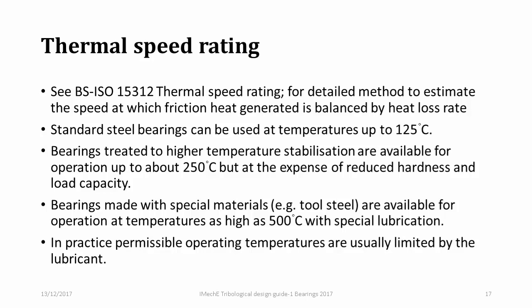Standard steel bearings can be used at temperatures up to 125 degrees C. If they are taken higher than this, it's beyond the tempering temperature, and the body of the steel may start to change. So it's necessary for those circumstances to heat treat at higher tempering temperatures to stabilize the bearing for that sort of operation.